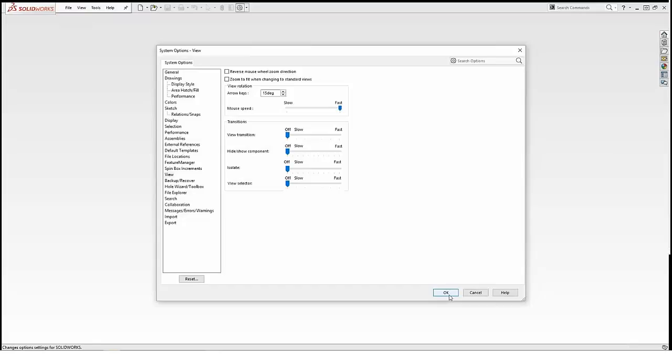And then another big thing is you always want to make sure that you're starting these modeling practices at the part level. That impacts your assembly, that impacts your drawing. If you're seeing performance issues later down the road in a drawing, we can probably go all the way back to the parts in that assembly and see things that were done